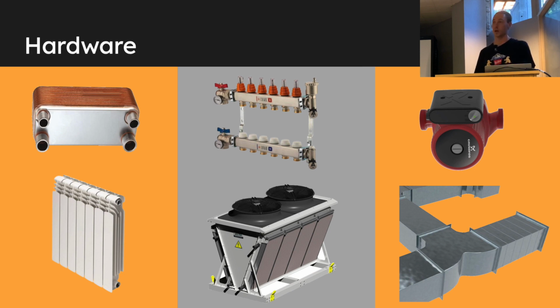You could also do it this way. This is kind of how a lot of plebs have done it, strap it into their house. And I also think it makes sense for warehouses, things of that nature. We don't have to transfer the heat over such large distances. Also, when you get to large distances with liquids, the pumps can get very expensive. It's a large pressure head. You ever try to suck something out of a straw? The longer the straw, the harder it is. It's the same thing. So when you start pumping over thousands of feet, you need multi-$1,000 pumps to do that.